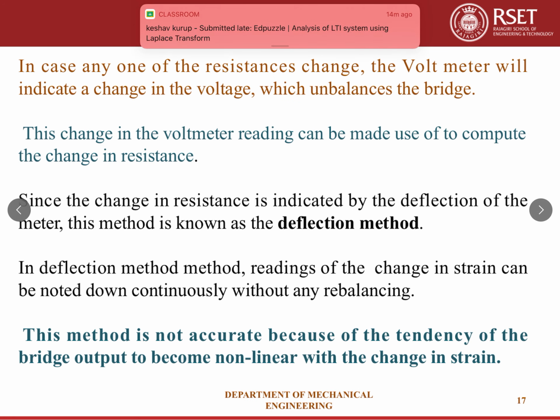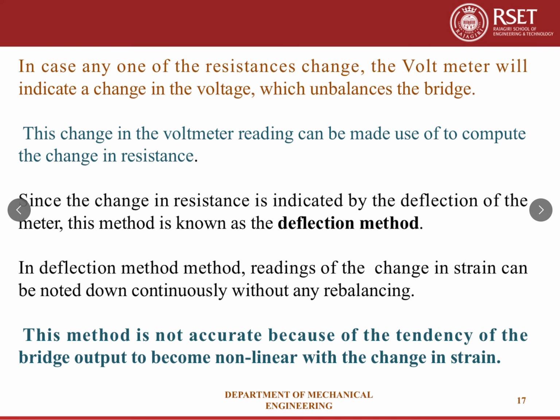In case any one of the resistances changes, the voltmeter will indicate a change in voltage which unbalances the bridge.